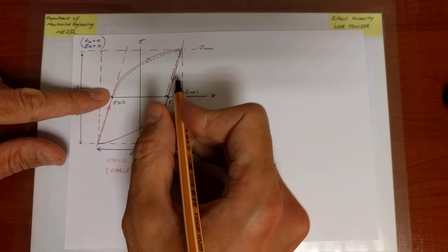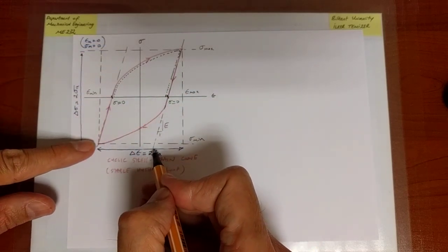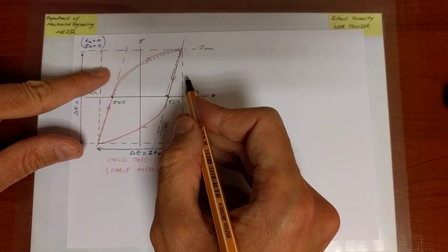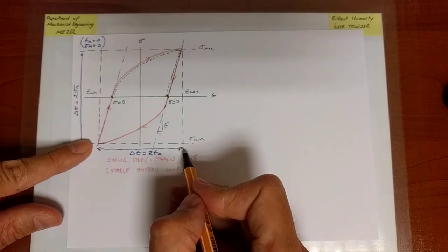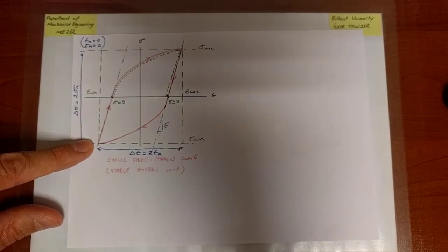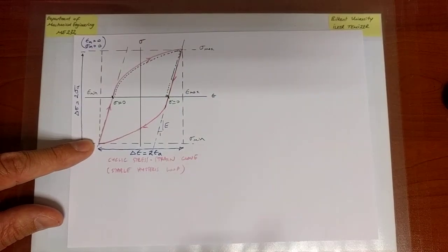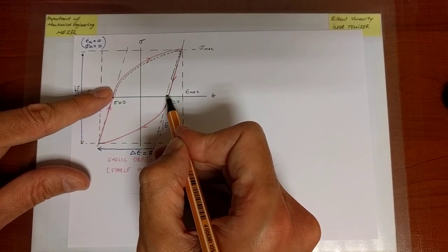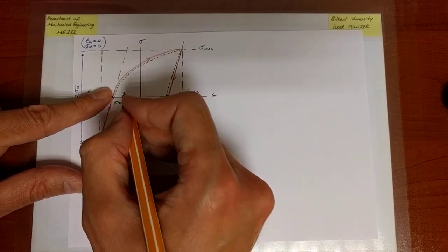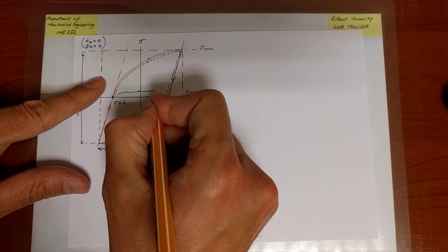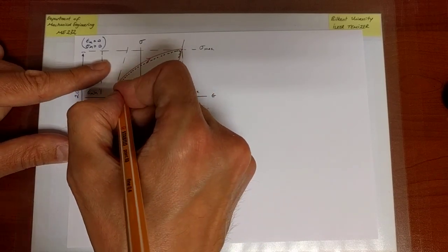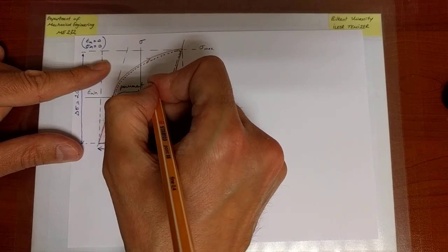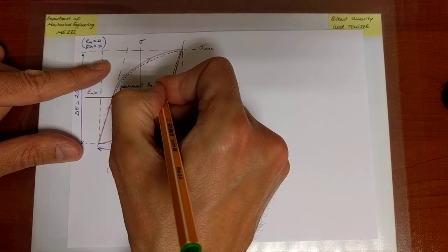And this distance, when I follow these parallel lines, is a portion of the overall strain. So there's the overall strain that we are imposing on the material, and that overall strain has a portion that is associated with permanent deformations, which we had always indicated earlier or defined to be the plastic strain. So this is permanent length change.